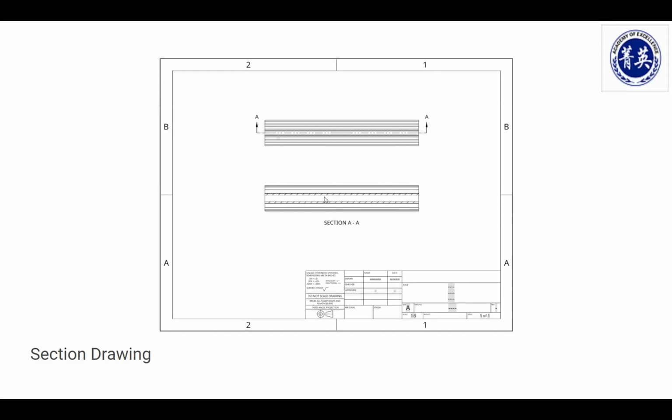To show what it looks like on the inside, we talked a little briefly about a section drawing, right? So A points that way. What that means is it sliced this model in half and is looking in that A direction. So section AA shows what that looks like. The little diagonal lines that go down the chain there, that means it's solid. Okay, so you have a solid side and the core hole right there and some other side over there.